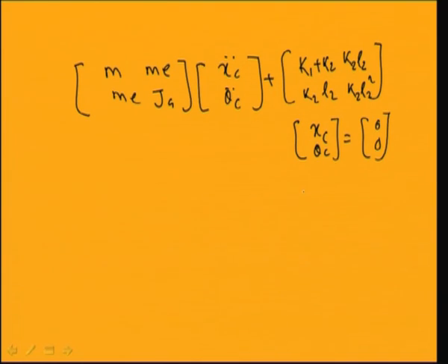So by changing the position of the coordinate system, you can make the system a coupled one or an uncoupled one, or you can get a statically and dynamically coupled or uncoupled system. Already I told you the coordinate system for which you get both dynamically uncoupled and statically uncoupled equations, that is, the mass matrix is uncoupled and the stiffness matrix is uncoupled, is known as the principal coordinate system.